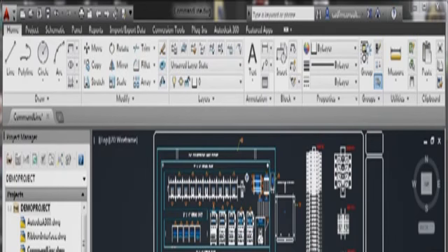So I can click on the sub-option settings in the command on the command line. That's been a new feature in the last few versions of AutoCAD. It's extremely useful, saves you having to right-click to go to the shortcut menu, saves you having to type, in this case, U for undo, and press enter. I'll just press escape there to cancel the line command. So the command line is, again, a very useful piece of kit in your AutoCAD toolbox.